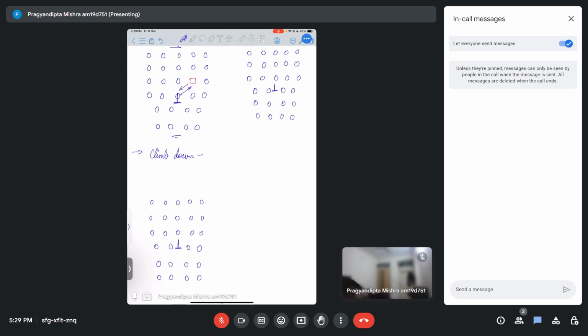This is the point where the dislocation is present right now. I can also say that at this point, I also have some sort of vacancy here, right? Because one atom is missing at this point.